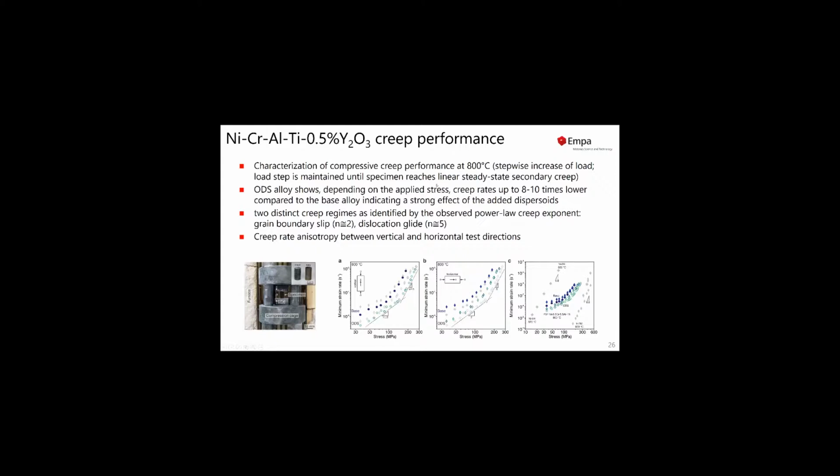What you see here is actually a comparison again between our base alloy and our ODS alloy. We tested the samples in both vertical and horizontal directions, so with regard to the building direction. And the ODS alloy, that was also interesting, shows, depending on the applied stress, creep rates which are 8 to 10 times lower compared to the base alloy, which indicates that we indeed see a strong effect of the added